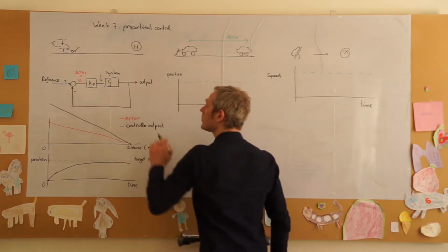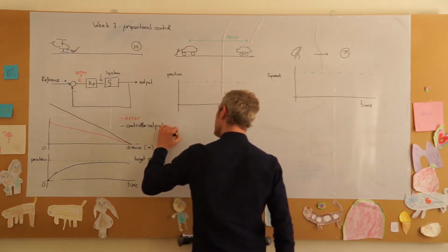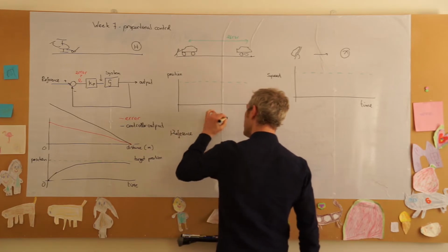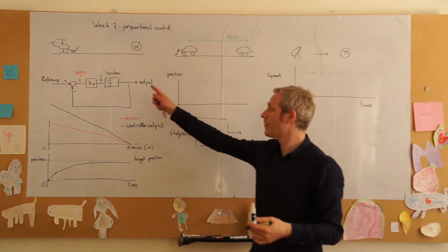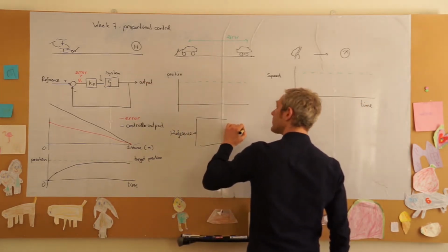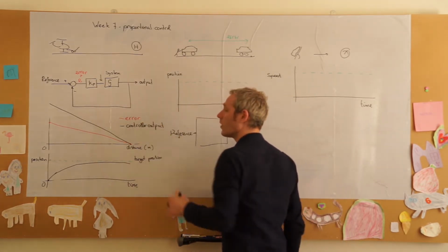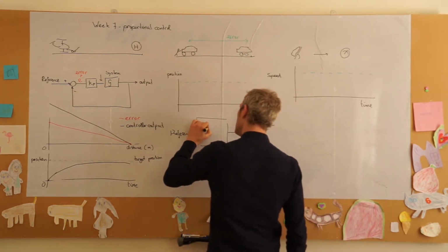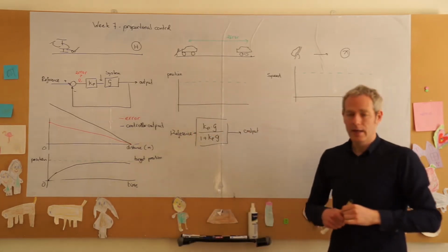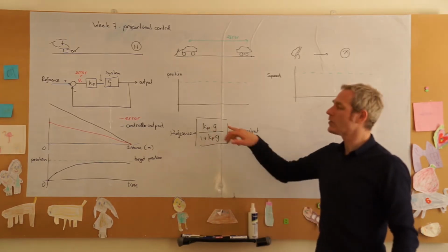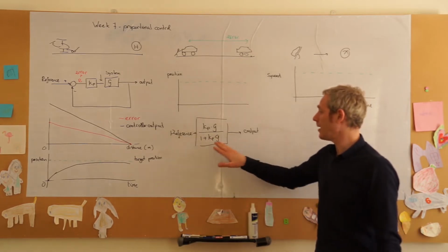we have a proportional controller here, we can replace this block diagram with the following, where we have our reference, we have our system, and this will be our closed loop system now, where I have replaced this whole diagram with one block. The transfer function of a system like this is Kp times G over 1 plus Kp times G. Now, we can see that for small values of Kp, this is not equal to 1. There's always a discrepancy between the output and the input.